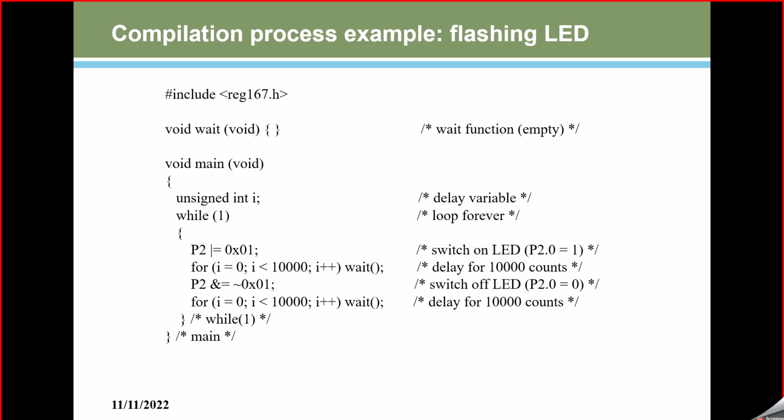So if that is the speed of the microcontroller, we will not be able to see physically whether the port or the LED is on or off. To see that the light is glowing or not, we need to have a delay between the on and off time. If the delay is there, we'll get to know, yes, it is on or it is off. To create such a delay, they have called this for loop and this dummy function.